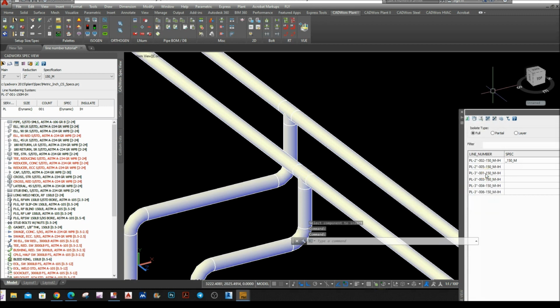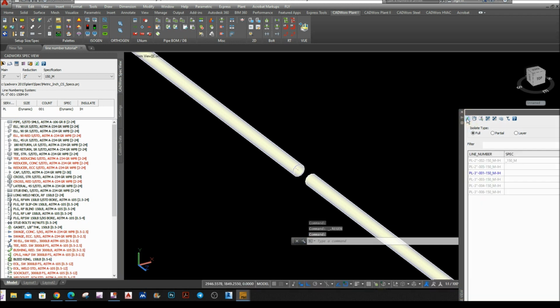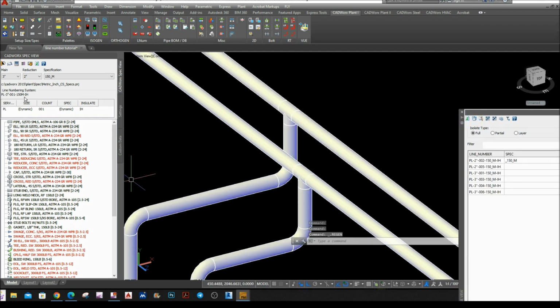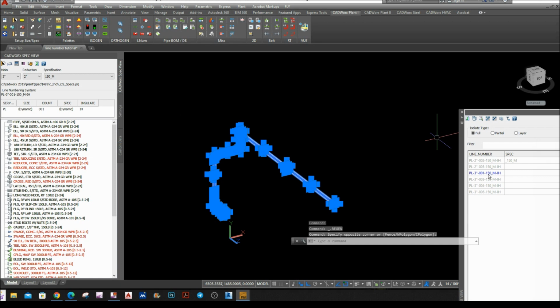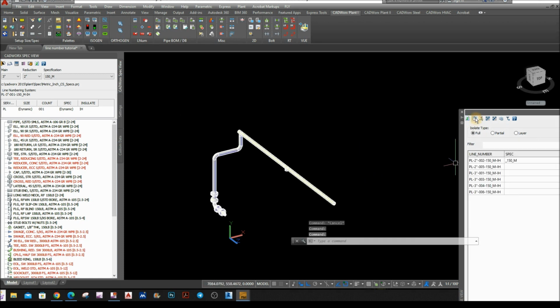So if I click this line here, and isolate items, I'm gonna refresh. Okay, again, 001, assign, click this T, and select yes. I'm gonna refresh this one. And then 001, isolate items. Now it's all the same. So this whole thing is 001. Now I'm gonna bring back my other ones.